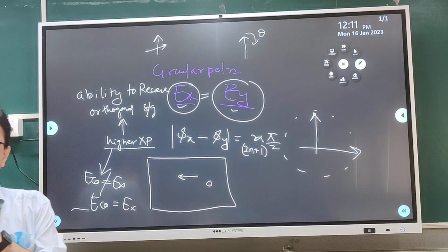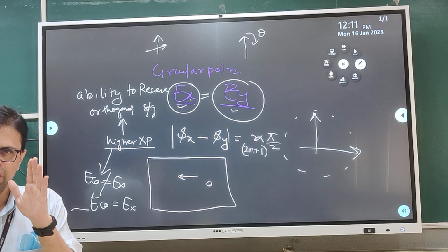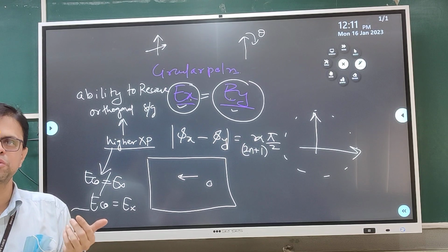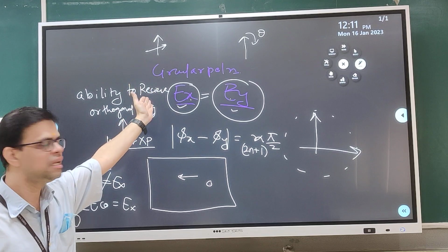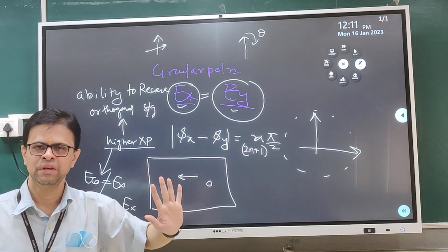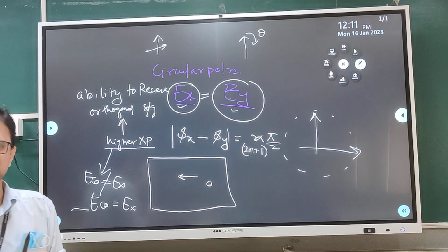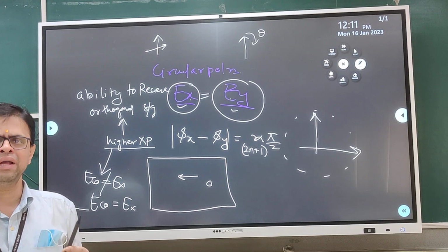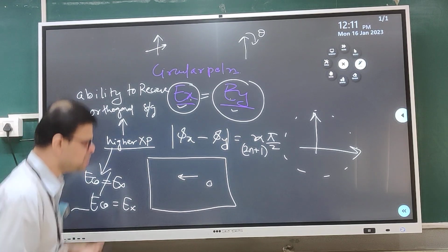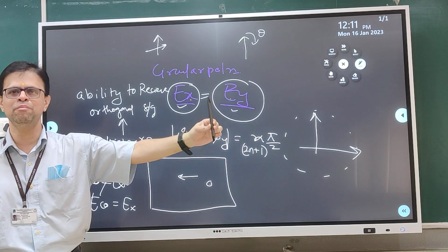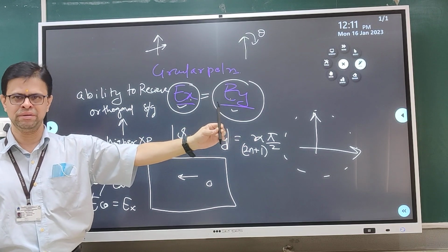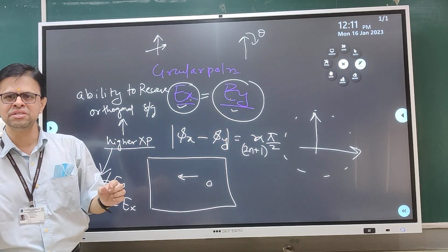I am trying to correlate here the radiation pattern measurement, or the cross polar and copolar measurement, with respect to the signals which are received in orthogonal planes. Okay, this is something very important. I'll just give you an example so that you can understand this. Suppose I have a dipole antenna as a transmitter. I have a dipole antenna as a receiver.